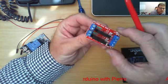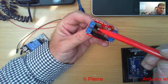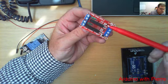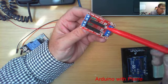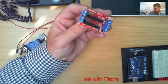Well, these solid state relays you can use to switch AC supply but not DC. So they are mainly used to switch AC. So you've got your DC input on this side, and you can switch an AC load on that side.